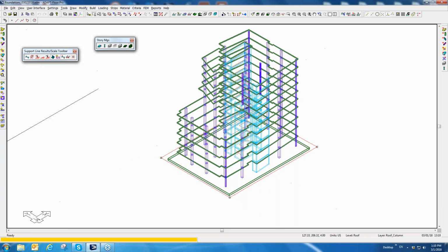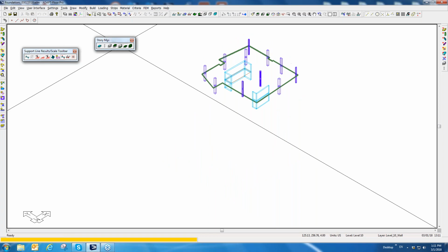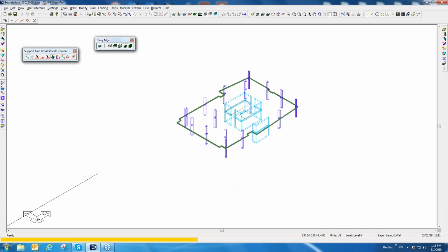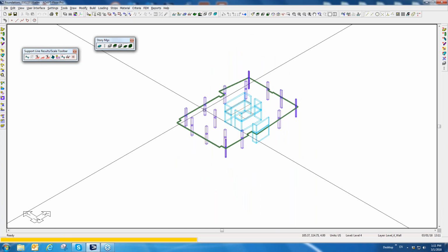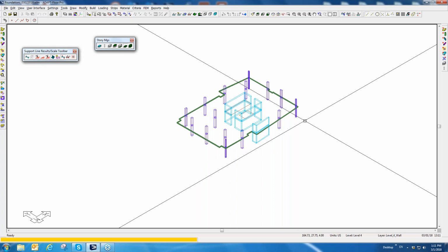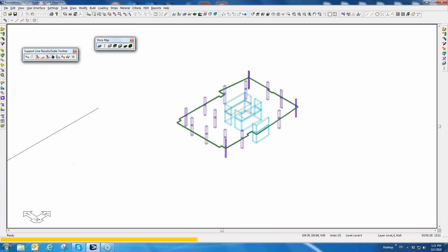the fact that at the foundation level we have a spring versus an elevated level. If I go to single level mode, and I'll just navigate down here, we'll say that maybe this level is a transfer. When I run this level, there's no spring. We're assuming that the base is fixed in the Z direction for a rerun of a single level that's elevated.